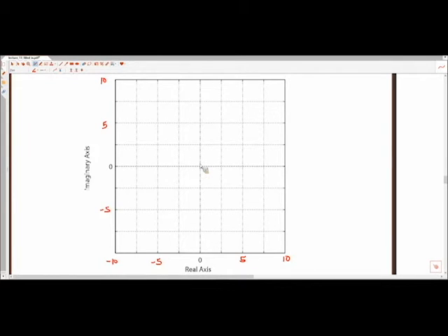So we have an open loop pole at the origin, right here, and then we have two complex conjugate poles, -4 minus 4i, which is approximately here. This is 2.5, so it's right around here. And then we have -4 plus 4i. So this is where our root locus is going to start. If k is a really small number, the closed loop poles are going to be really close to the open loop poles, is what this first rule is stating.